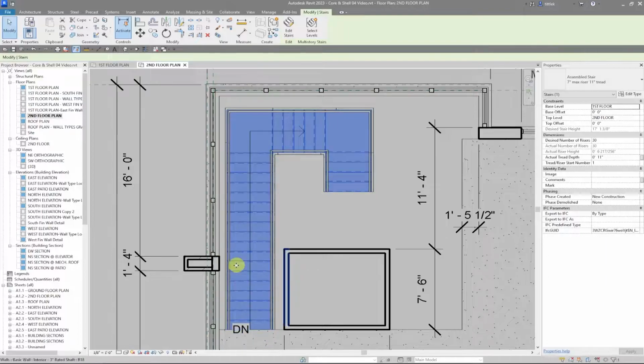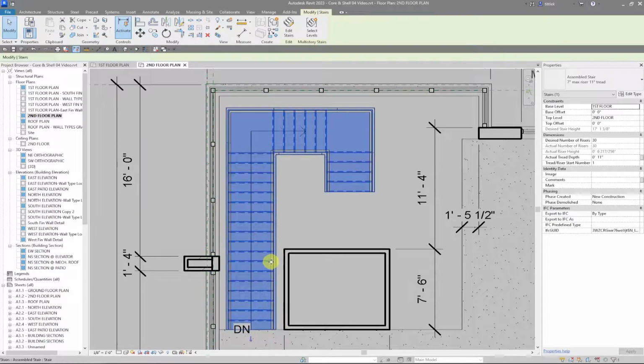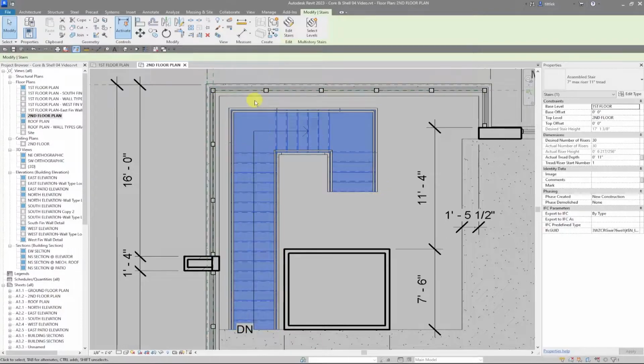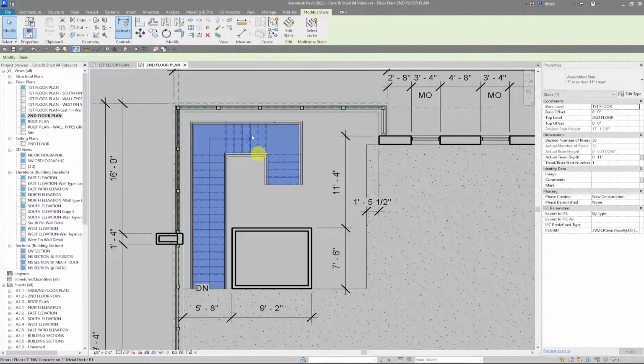It just needs to be between this exterior wall and this elevator shaft. It does end up being closer to the elevator shaft than the wall, so I'm just going to nudge it over about there. We will locate this entire stair to its final position once we get a column grid in a future assignment. Now, before I start making a lot of edits to this stair and railing type, what I like to do is create a view where I can see what the edits are doing to the stair so that I'm aware of the implications of my edits.